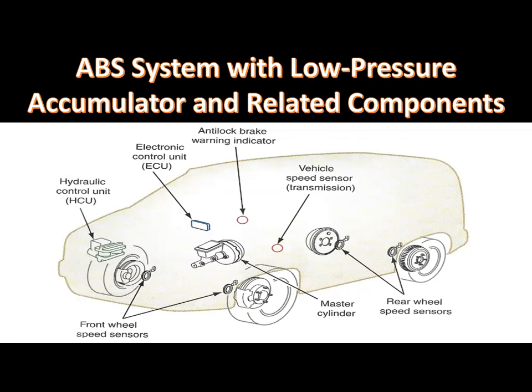During a prolonged brake application, the repeated cycling of the isolation and dump valves takes fluid out of the master cylinder and places it in the low pressure accumulators. For this reason, the control module starts the ABS pump motor when the system enters the anti-lock mode.